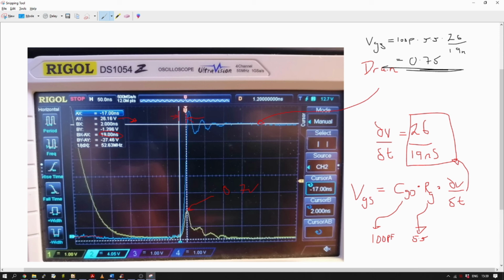So in actuality, what have we got? It's 1 volt per division, so there's a volt, and we're already a little bit over that, and there's another division there, yellow lines around about there, which says about half. So it looks like it's actually more like 1.5, so we're about a factor of 2 off. That could be most likely due to this not being the best method of calculating the time, but it's not too bad.